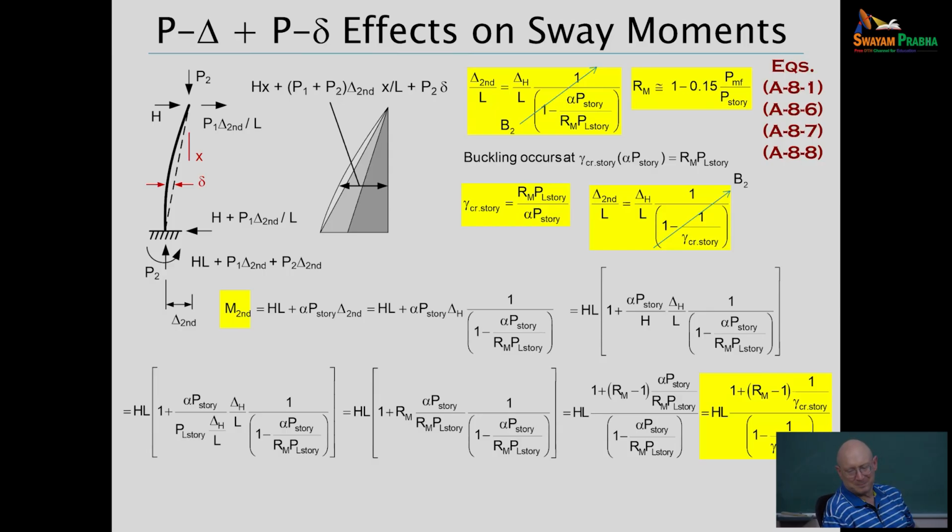Yeah, on the sine curve, we did make the approximation to derive the Cm. We needed a function for the deflected shape to get a small delta. So we basically took the buckled shape form. But that's a reasonable assumption, right? Yeah, reasonable assumption. The Rm is a gross approximation.